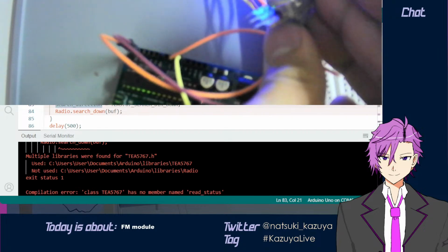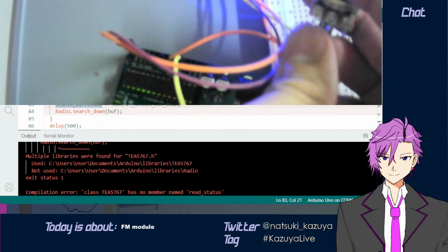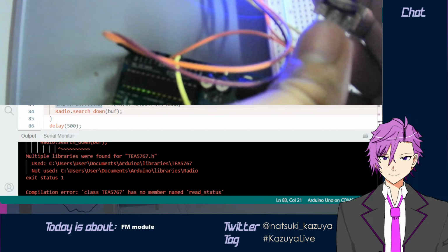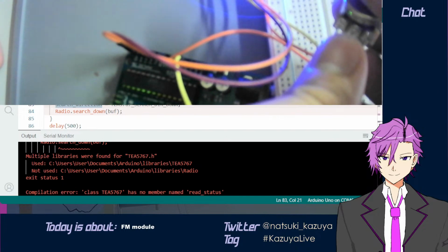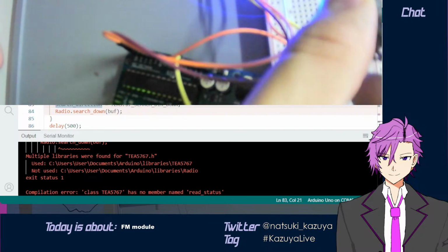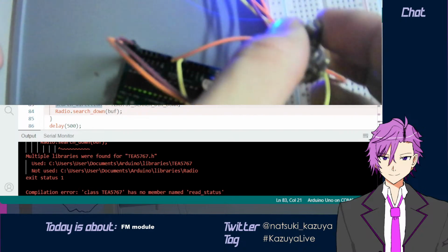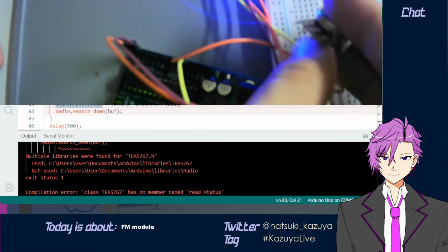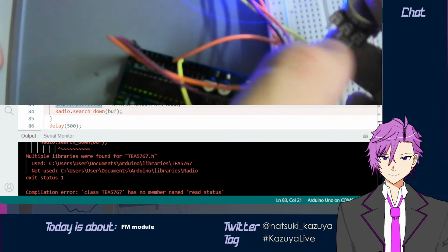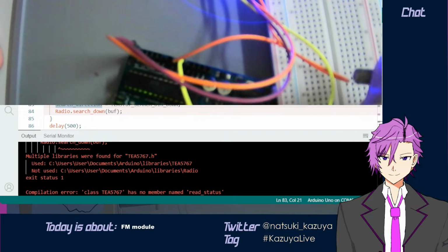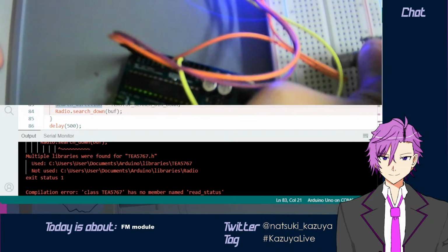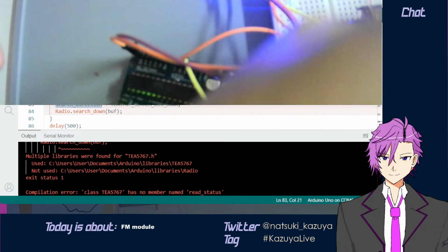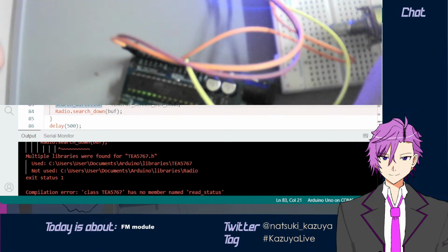Speaking of which, there are 3 terminals in this pot, I think. Yeah, there are 3 terminals. So the middle one is the compulsory terminal that you have to connect, because that is going to be the one that adjusts how much resistance goes into your system. And you can choose either one of the other terminals to connect to your system. So put this. Yeah, that's not even a final product, is it? So hold on, let me find